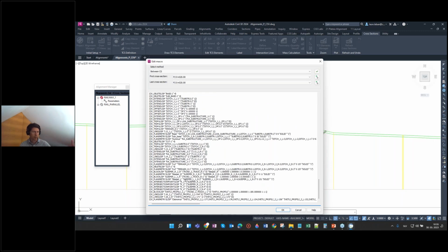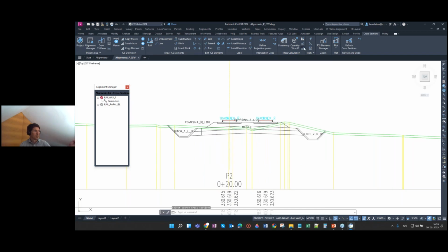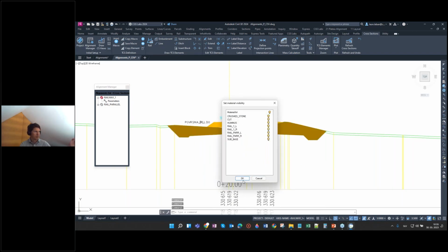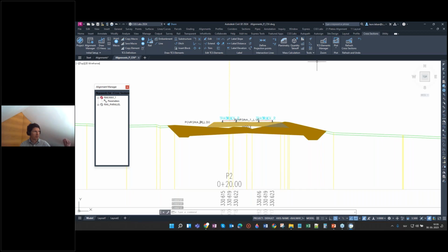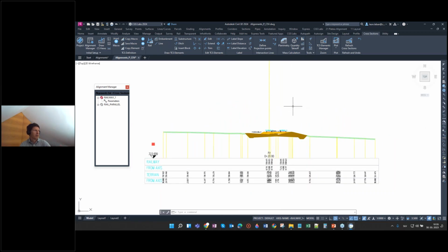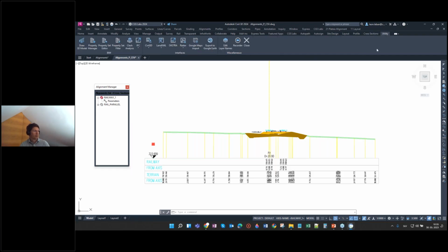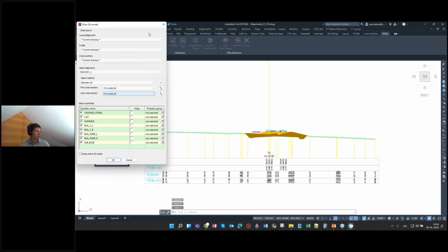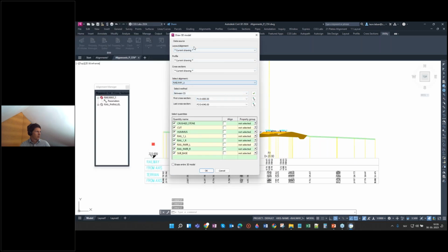So you see there's a lot of work that has been done to define everything, including the materials, right? So the cut, the fill, and all those details. And this makes it the base for your next step. So we've now done all the 2D analysis, design, and detailed setup of everything. We simply go to 3D now. We see that we can read the data from an existing drawing. Okay, we will align those.